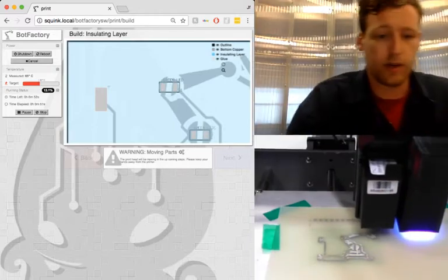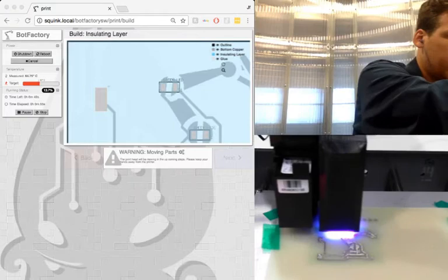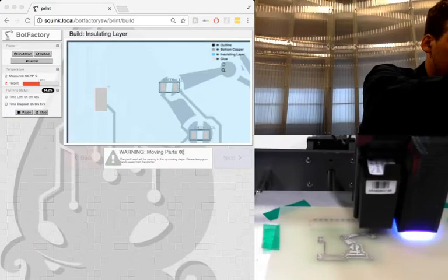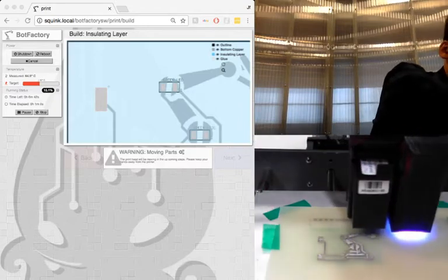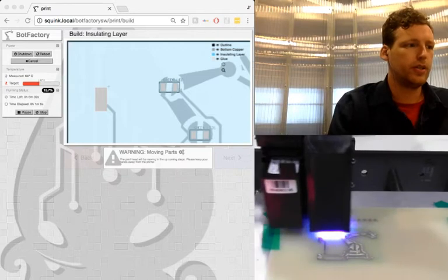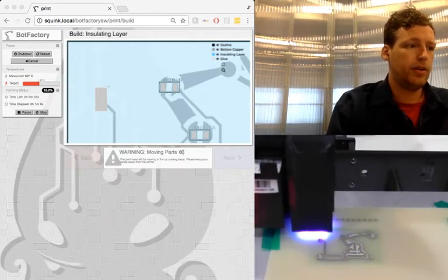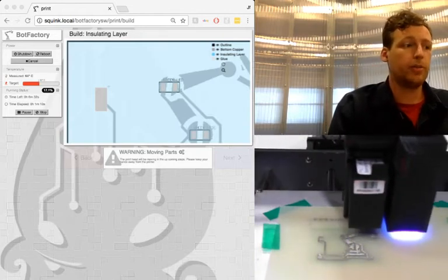So you see what's going on, right? Let's just take a look at the view. You can see our UV lamp is essentially curing the material after it prints. What happens is we print, and the head moves back, and the lamp basically binds the material. Typically only 2 passes are needed. If you're running low on ink, you might need to do 3 or more.